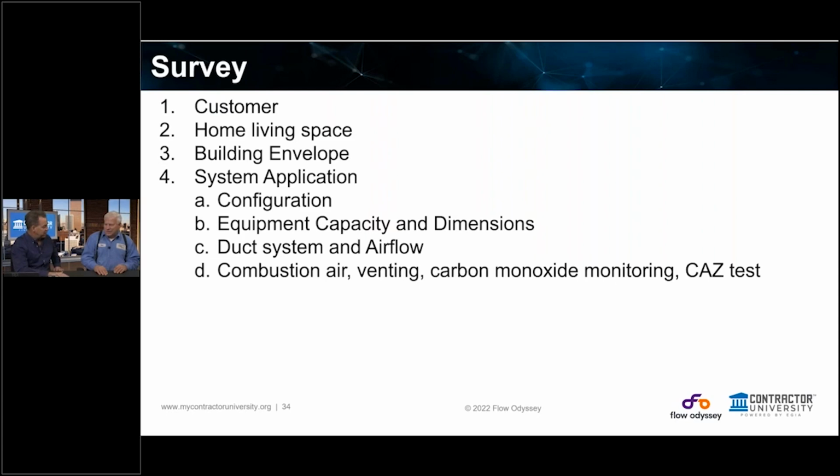Talk about venting, right? So we get into the house, and we have the thing that we're inheriting that we're going to get rid of. We talked a little bit about this yesterday, right? We're going to basically put in a 90%er, but we're going to orphan the chimney. Then you have to put a flue liner down or something to make it smaller so it heats up quicker. Which makes zero sense, because what you spend for the flue liner, you might as well invest into a brand new direct vent or tankless or heat pump water heater, right?